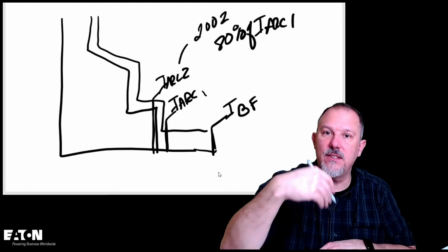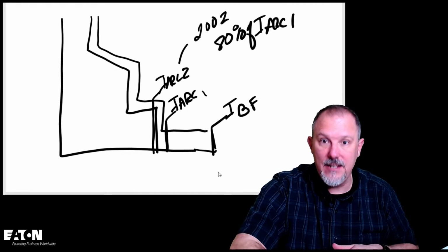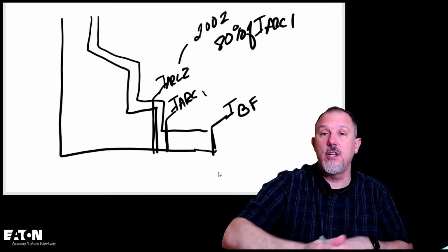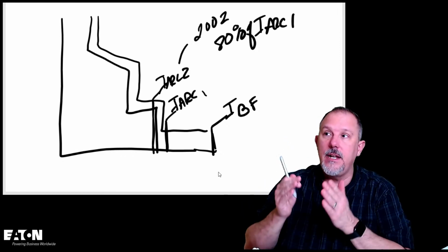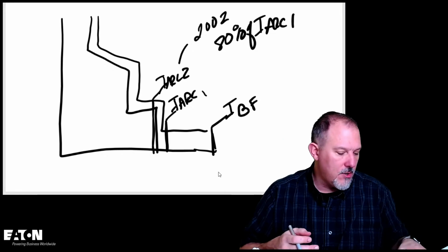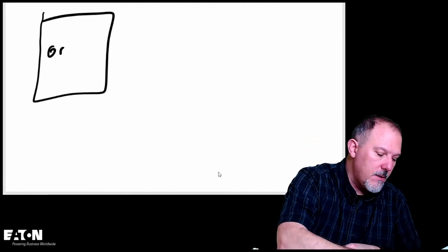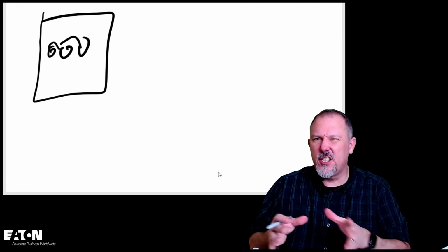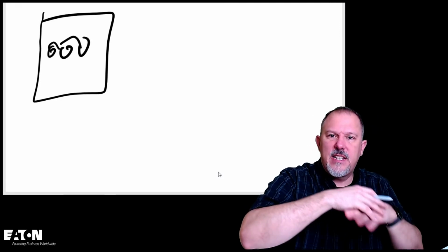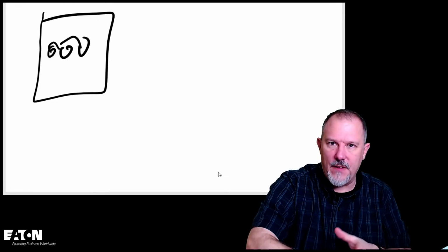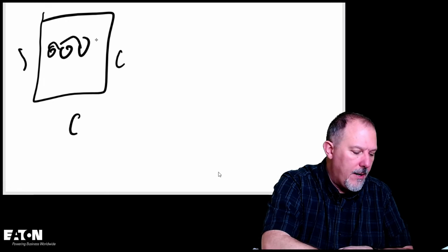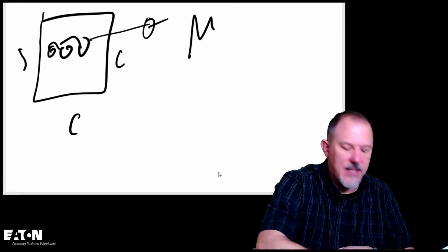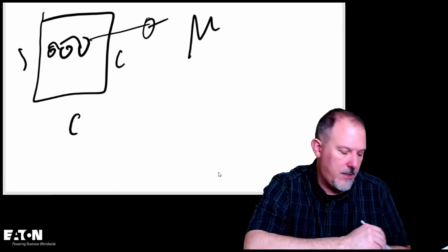In the 2018 version, Dr. Lee developed equations to calculate both of the arcing currents. How do we come up with the equations? So here's what we do. We take a box, and call it arcs in a box, and we create an arc flash event. We put all of these little calorimeters in front of it. We measure the current to get the sine wave and all that jazz.